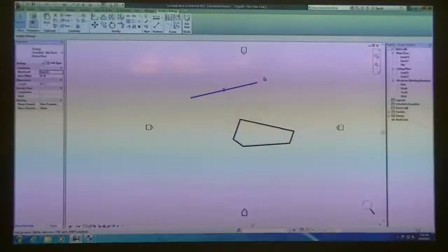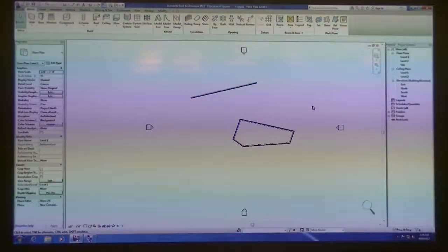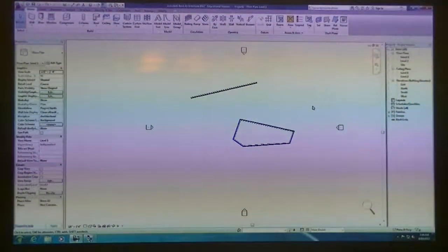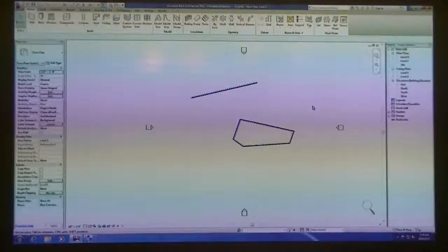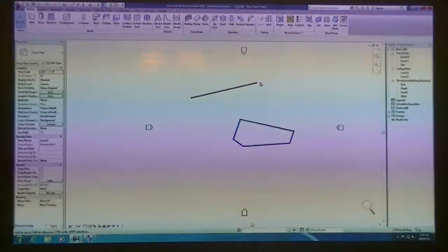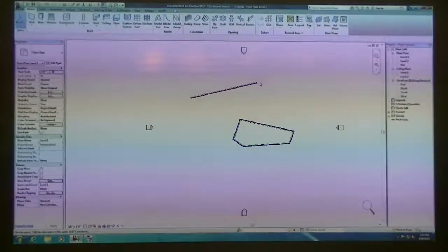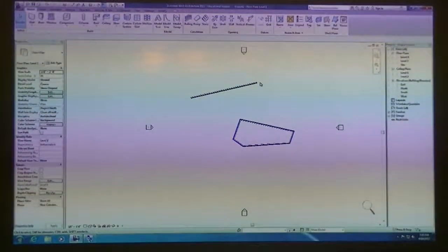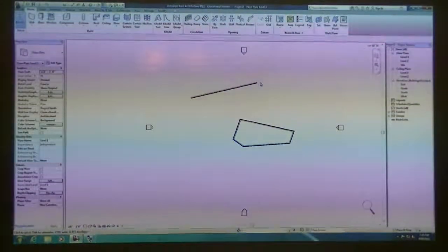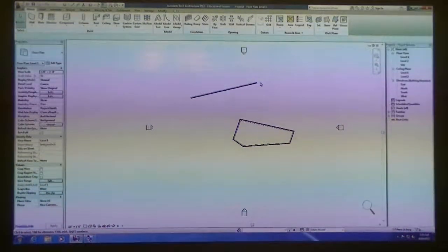So if you've made different railing designs in other project files, and this goes for any component that you've made in Revit that is not a family component, because remember the railing was developed by the railing tool that's in the project environment, so it's specific to that project. If you ever want to bring in, let's say you created some stairs and changed all the different profiles, which we'll need to do in another class, all of those stairs or whatever different parts you've made, I could have that in another project and you can copy and paste it. As long as you have both open, you can load them into the projects that way.